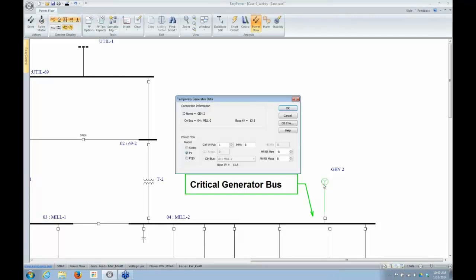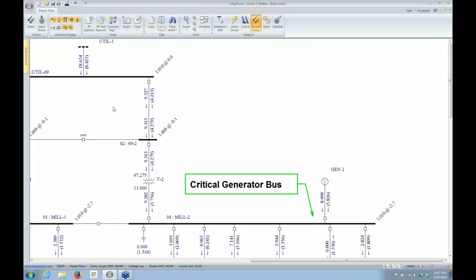So again, one of the things to look at is this. I'm suspicious that this probably is creating a problem for us right now. I would increase this to some much larger value temporarily to see if I can get it to converge. I might change the voltage. I see I'm trying to increase the voltage here to 1.01, but I didn't change the voltage here. So that's another issue that you might get into. So 1.01 for both, then it ran. So you have to make some adjustments to your system to match the real world situation to get this to converge sometimes.